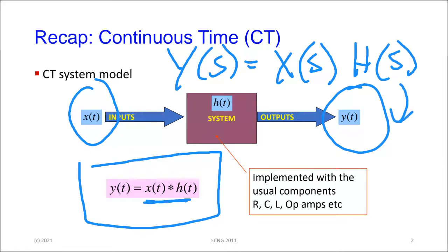This, of course, we call the transfer function, right? But just to illustrate, there were some things, for instance a simple thing like a rectangular pulse. Trying to get the Laplace transform of that is harder than trying to convolve it with another rectangular pulse. It can be done, and there are some past paper questions that ask you simply to show that if you were to use the Laplace transform to convolve two pulses, you get the same answer as if you were to use the manual approach that we did in lectures 10 and 11 kind of thing. All right?